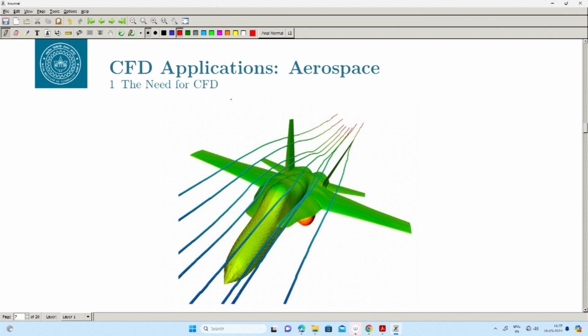So, you can do the simulation by parts, in the sense that you could do the simulation on a wing separately, the empennage separately, and the control surface separately. You can put a wing with a flap or a slat and see how they change the dynamic characteristics. You can do a simulation on a fuselage separately, and once you are satisfied, you can put all those components together and do a simulation of the full model.